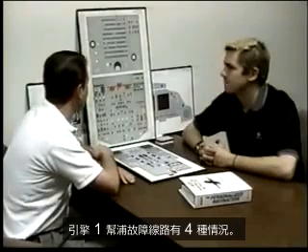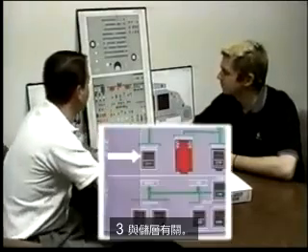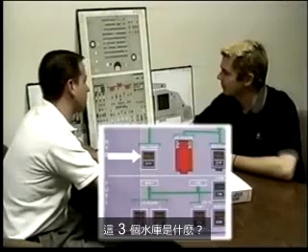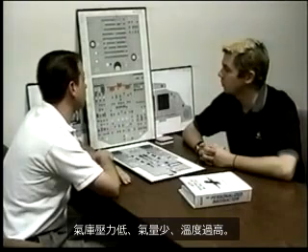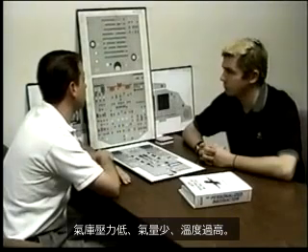4 conditions for a fault light on engine 1 pump. 3 are associated with the reservoir. What are those 3 reservoir conditions? A low air reservoir pressure, low quantity, and over temperature.